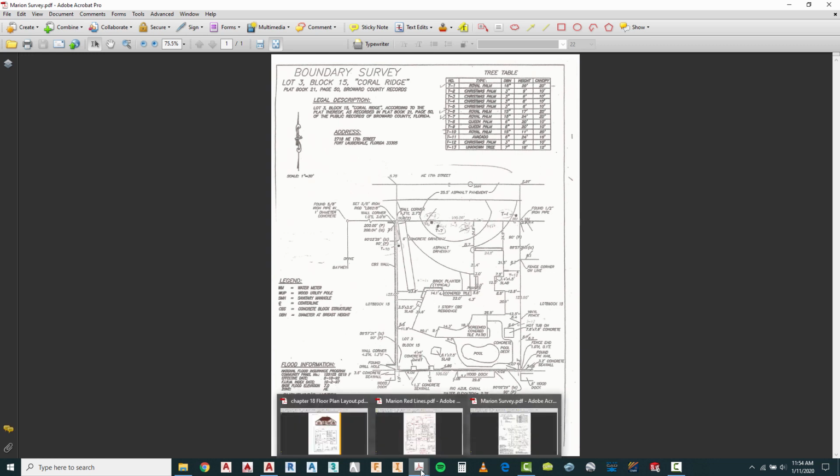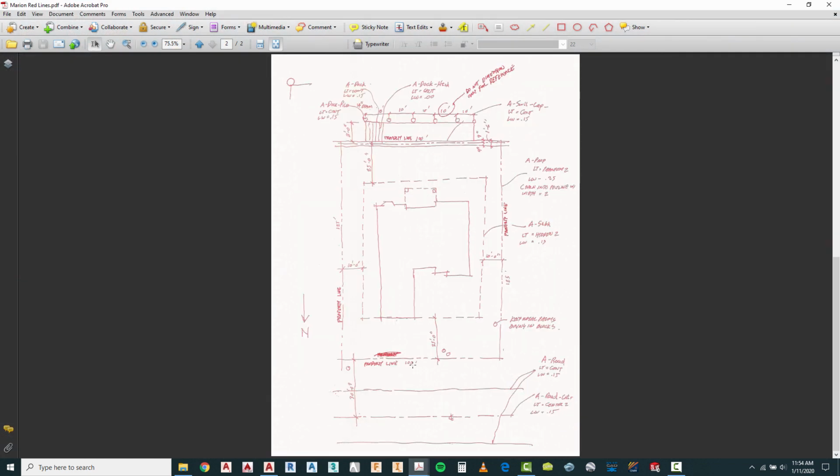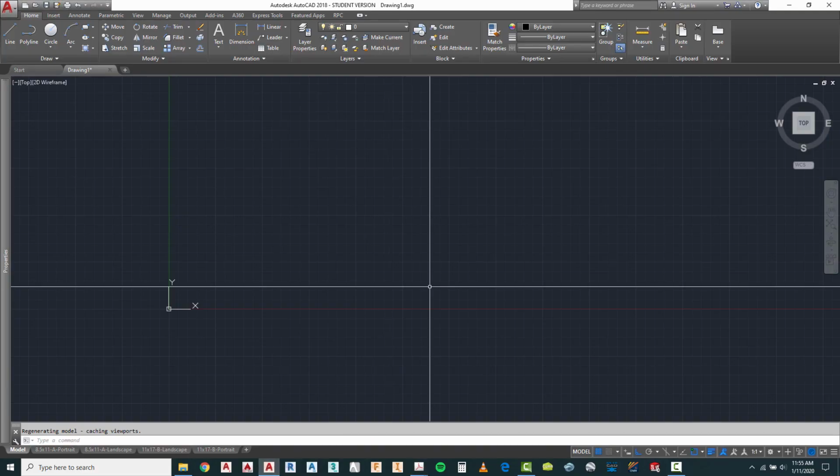I have also included on the markups in here a set of instructions for our site layout, including information that we will get from looking at the zoning code, including setbacks on the side, setbacks in the front, how and what layers we will be using, including thickness, line type, etc., for property lines, docks, etc. So, with that said, let's go back to our